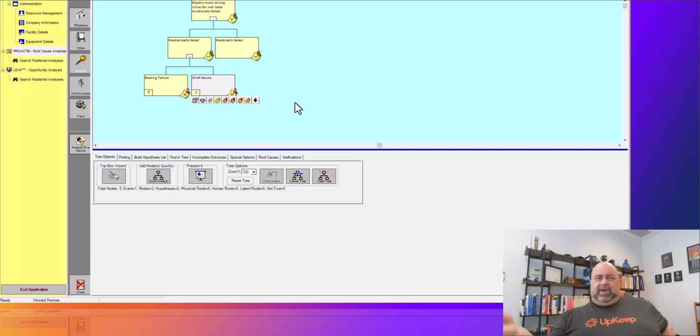And what ends up happening is we discover that the tear sheet for that oil says specifically, whatever you do, don't use Viton. And it was a Viton seal. Matter of fact, all of the gaskets and seals had been converted to Viton because everybody thought Viton was impenetrable to everything.